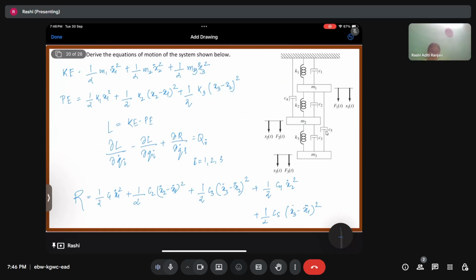In the two questions that we did earlier, the first question was about an undamped, unforced case. We had a 2 degree of freedom system and we were supposed to find the solution. Firstly, we found the solution in a general fashion. Secondly, we solved the equation using modal analysis, wherein we found the modal frequencies and the corresponding eigenvectors.